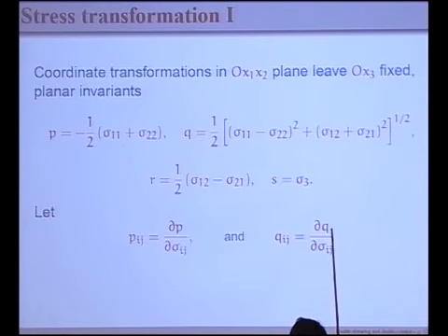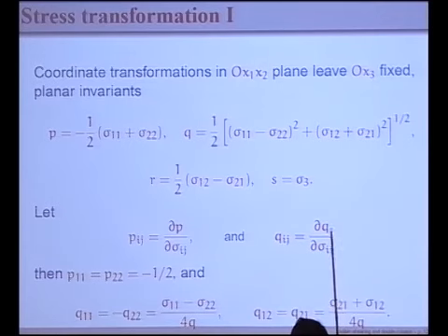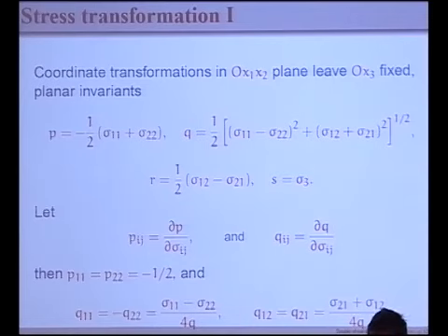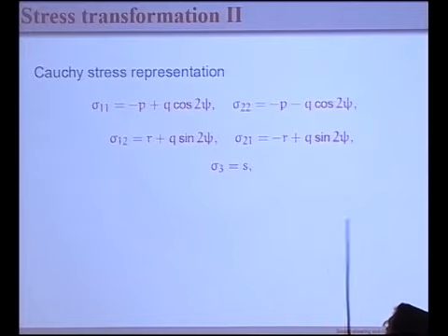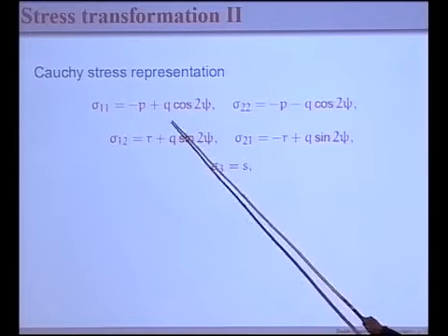So, in order to show that the yield condition contains all the characteristic information of the model, we can go through and calculate these second order tensors. And then, in these Qs we have the differences and the sum of these stress components.